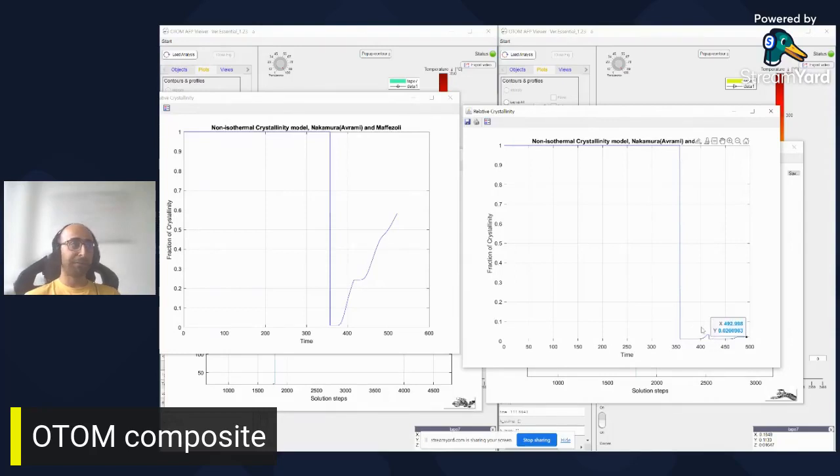This is a very important factor, especially for automated fiber placement, because in this process we remelt the material several times. We melt and remelt the material, and we cool the material again. This phenomenon of cooling and melting happening many times brings more complexity to the crystallization evolution and also crystallization melting. This becomes more complex for more complex geometry, more complex layup, and also larger shapes.